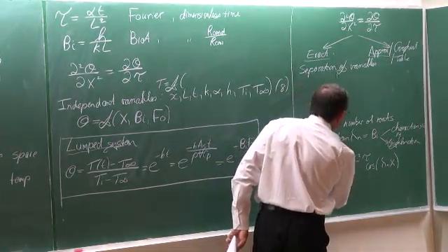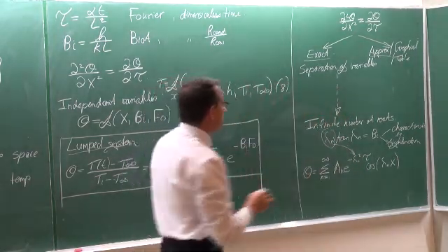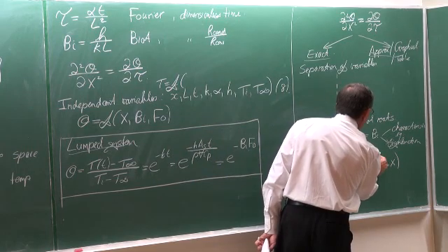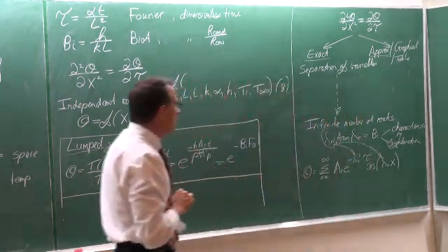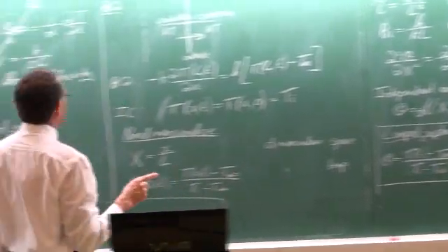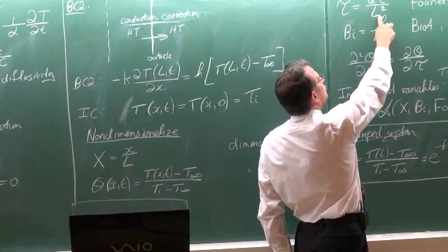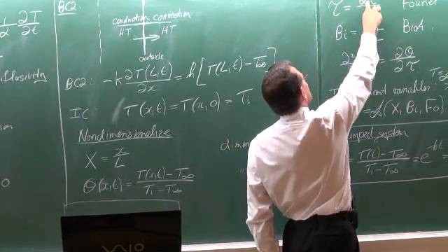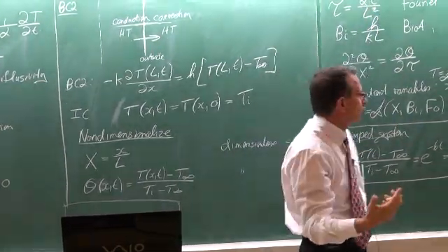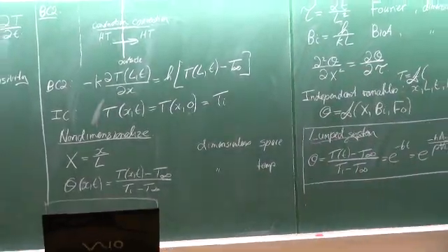We need the solution of lambda n to put into there, and also for that term there. Tau, remember, is the non-dimensionalized time. So if we want to know the temperature after 10 seconds, then it's easy to work out tau. That is not a problem.